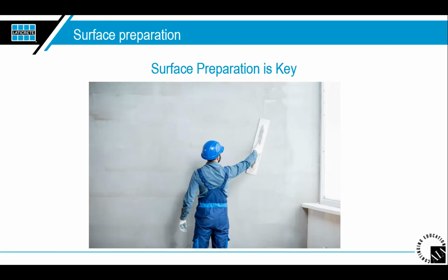And we see this all the time, especially in commercial applications, sometimes residential as well, where the tile setters will actually be setting tile in rooms where they might be drywalling or spraying. And whenever you're talking about drywalling, you think, well, how would that interact with the tile installation? But if you're sanding down those walls, that dust that's falling on the floor, if it's not being cleaned up properly and mopped up, we could just be setting tile to a layer of dust on the floor. And then we get the call from the ownership group that says, why is my tile delaminating from the floor?